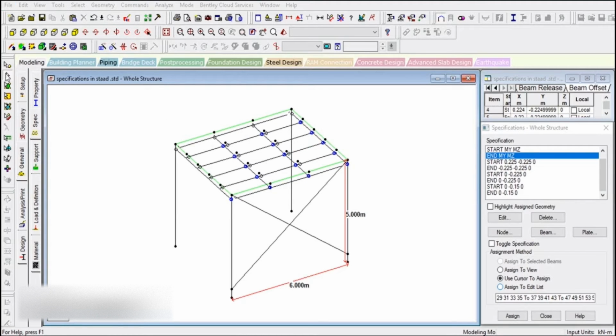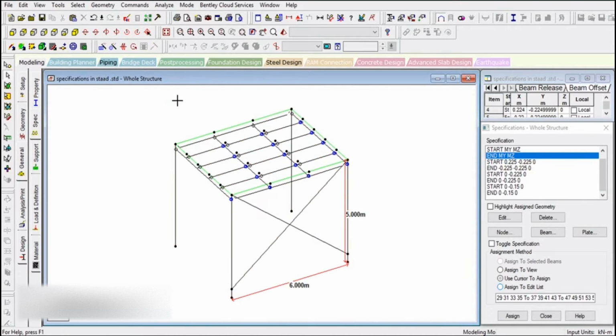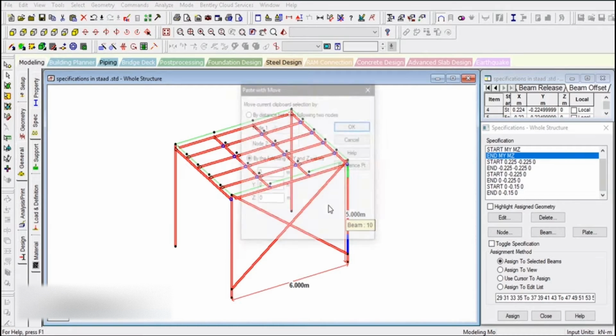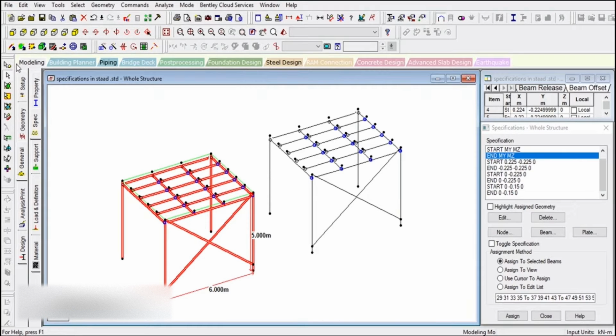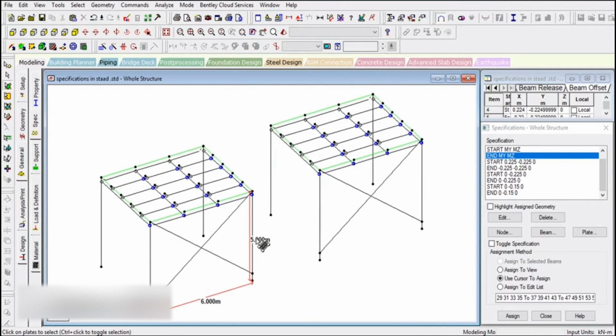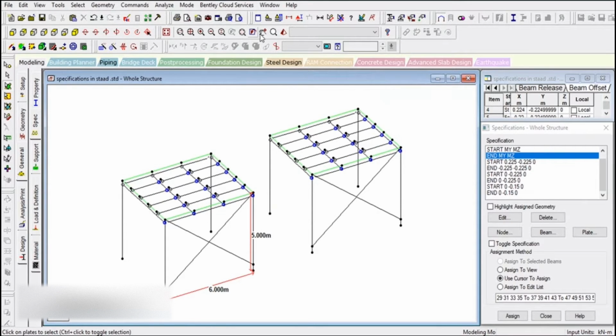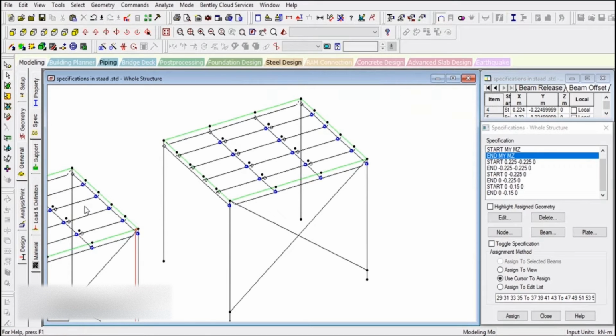So either we can go to file and save as the structure, or what we can do is that we can copy this whole structure here. Let us select 10 meter. We need to select the plates cursor here also, and same procedure, Control C and Control V, and then left click on 10 meter. So we can do the experimentation on this structure only, and if things go bad we can go back to the structure. So left click on plates cursor here.